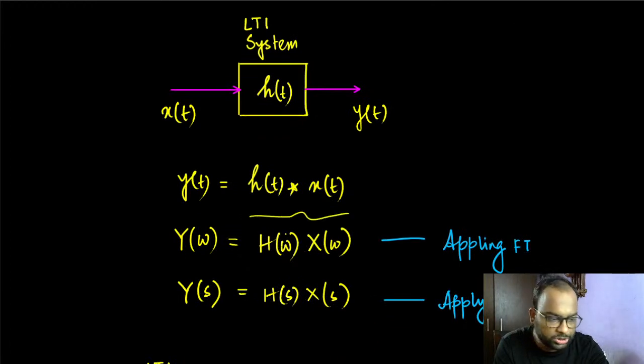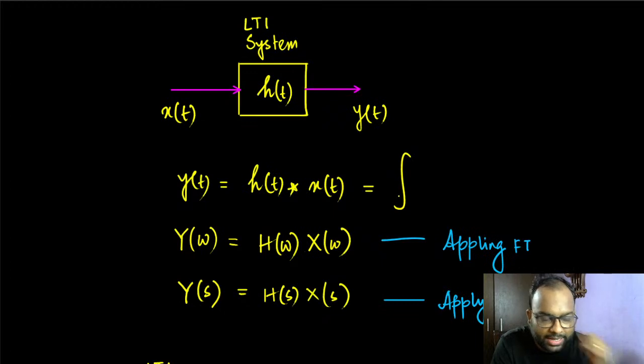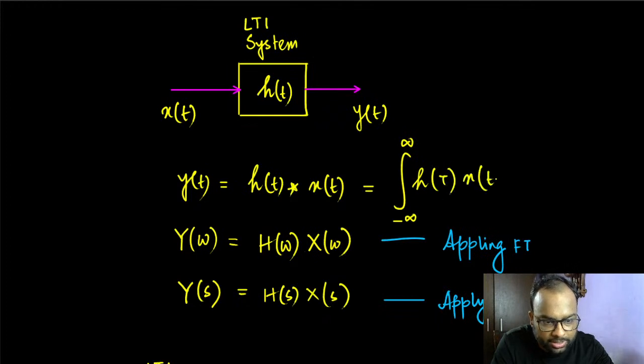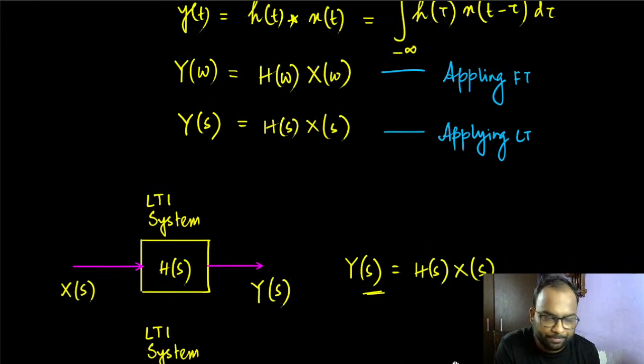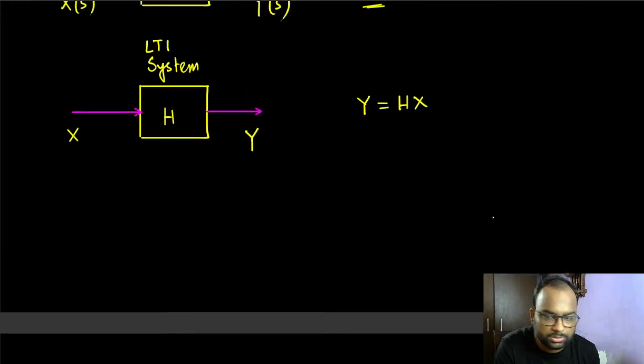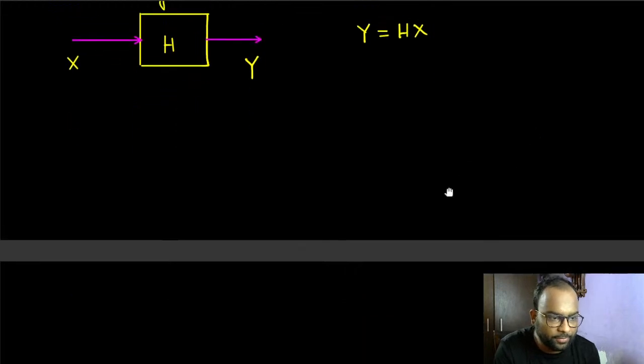found through the convolution. Okay, let me just write down the expression for the convolution. Again, we're considering linear time invariant systems. So the result is the integral of h(tau) x(t minus tau) d tau, or the other way around, you could write x(tau) h(t minus tau) d tau. So that integral would have been done. That's quite understandable, I believe.